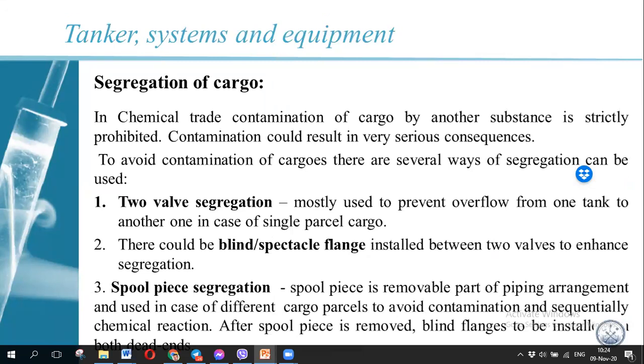Contaminated cargo is very big trouble. The chief officer, captain, and even the duty officer can go home without any relieving. So why is it important? You must always have two-valve segregation, minimum two-valve segregation. That means one valve could be spoiled, could be leaking, but the second one must protect your segregation.